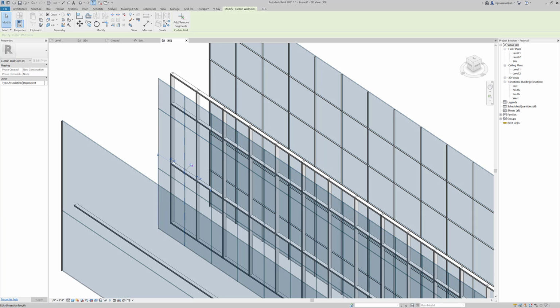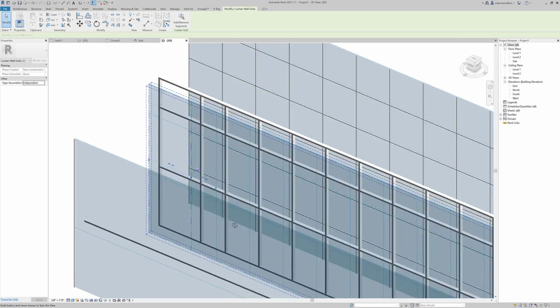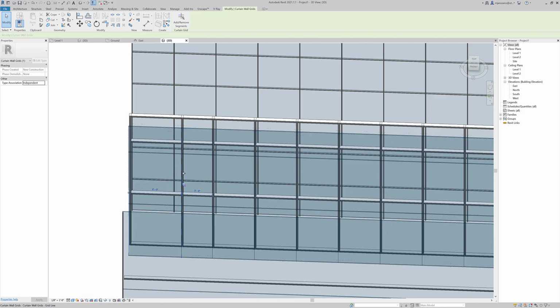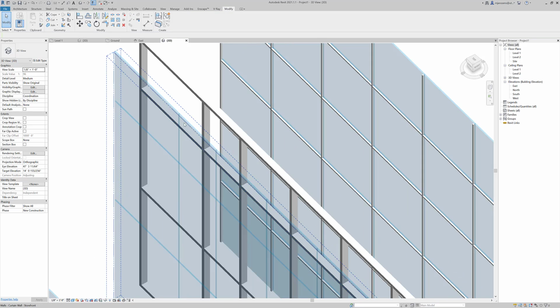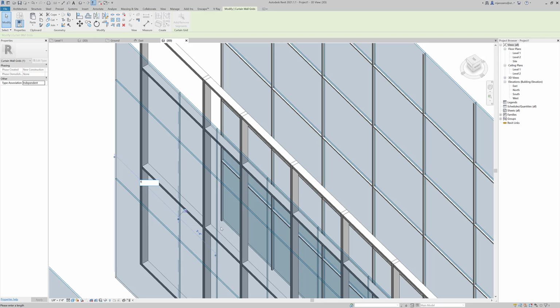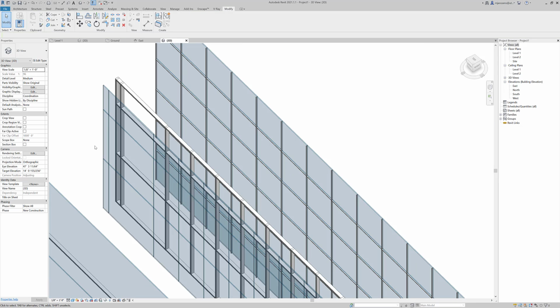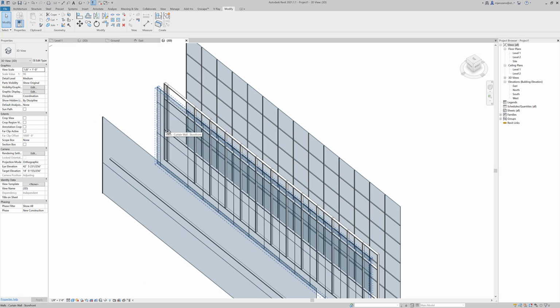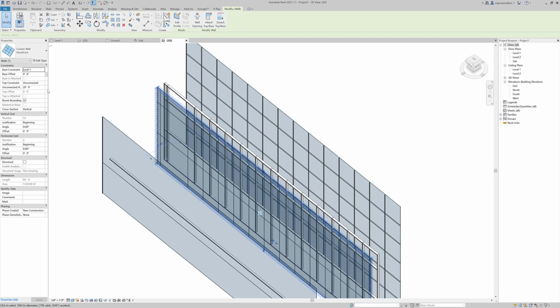these systems as well. So you can choose individual grids within the system. So if you have just one pane that's slightly larger, you can always tab over to get to that grid line, and then you can change its dimensions. So there's a whole series of control that you can have here, and again, it just is based on the amount of time that you want to spend on this. If you just put in a storefront, you got some mullions, then we'd be good to go. You could just put that in and modify it based on its height and its location, like a normal wall.